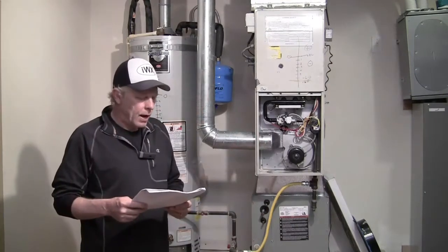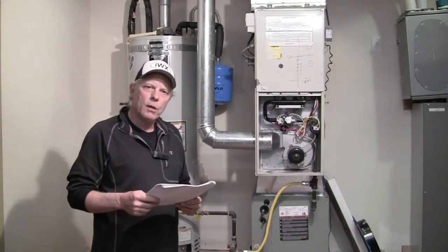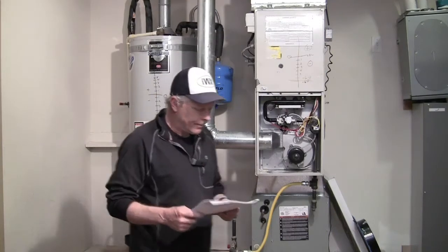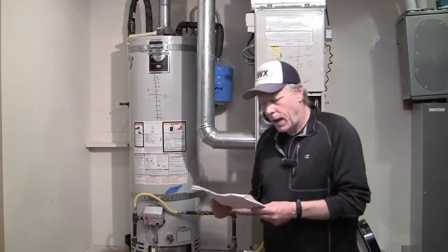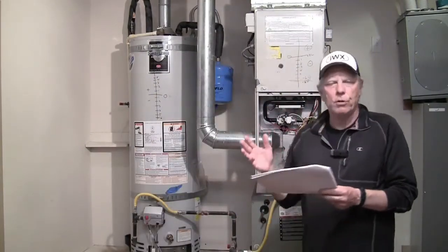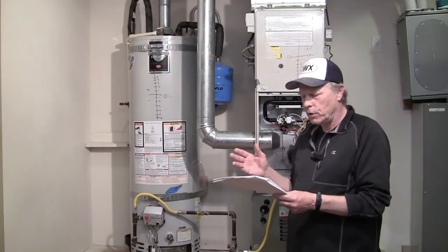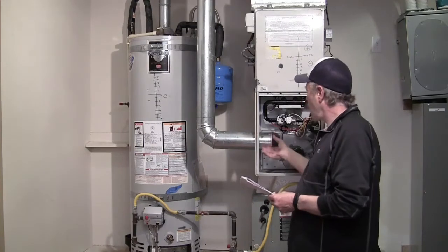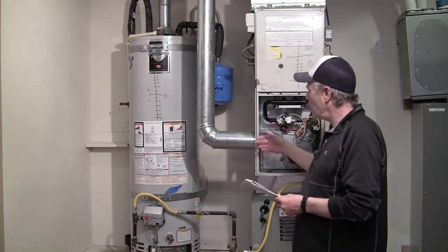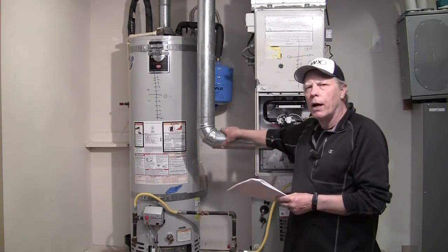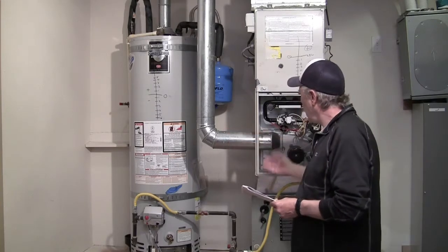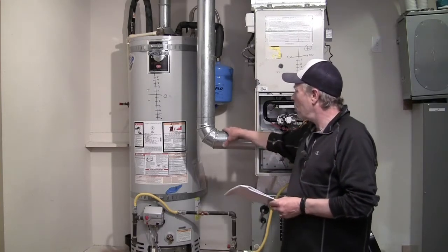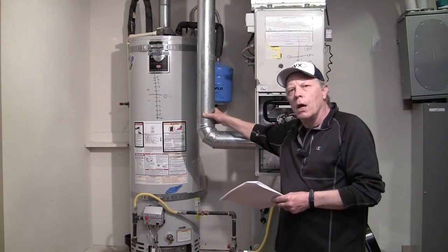We're on line 5 of heating, cooling, and domestic hot water equipment. This asks the candidate to complete a visual inspection of the appliance flue system. And right now where the camera is, you can see this lower part, and we're just making sure that it's connected and it looks right, that it's not corroded and that it's connected securely. So down here it is.